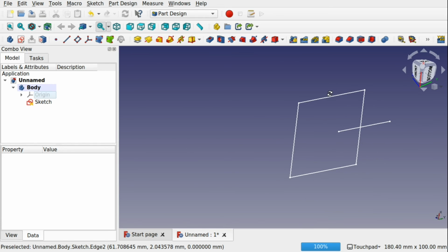So if you think about it, if I gave this to you and asked you, right, could you cut that out? That was on a piece of wood, and this is the line you've got to cut around. What do you do with this piece? Do you just cut through it into here, or is this a slot? You can't leave this here, you can't cut round that because there's nothing there, it's just a line. So that's one thing you have to think about when creating geometry. When you look at it, if it's something like that, can you actually physically do it in the real world?